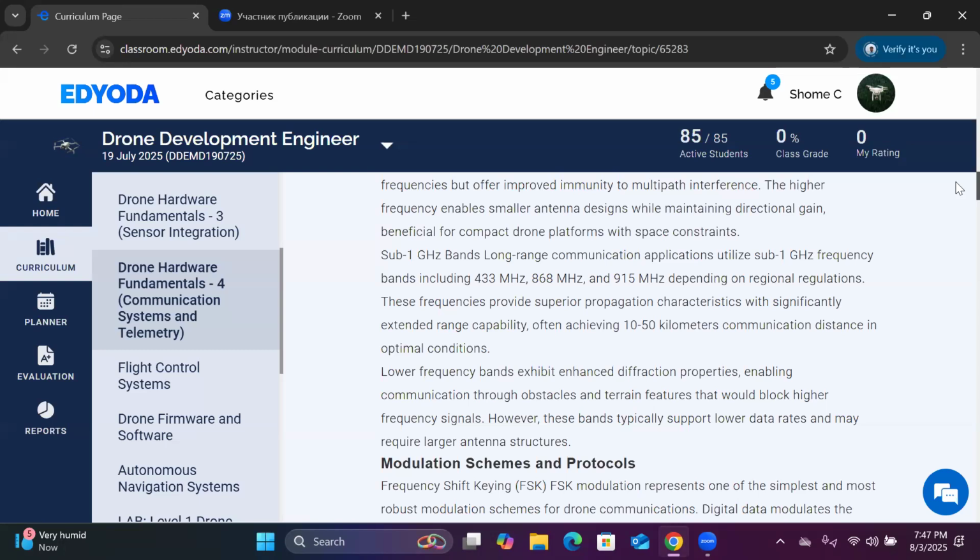Correct, bandwidth will be increased, the data rate capability and the computing power will be increased, a lot more processing power will get enhanced, and your RF power requirement will get enhanced. The RF power requirement that you had at 2.4 gigahertz will not be the same for 5.8; even more boosting power will be needed. Right. Yes.